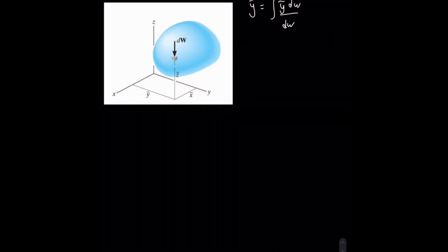It's worth noting that the center of mass acts in the same location as the center of gravity. So I'm just going to show that with this derivation right here. So you have W, dW is dm times gravity. Oh yeah, by the way, this is equal to the mass times gravity. So that's the reason for that. Okay, divide that by the integral. These g's cancel out. And then you're left with the center of mass.